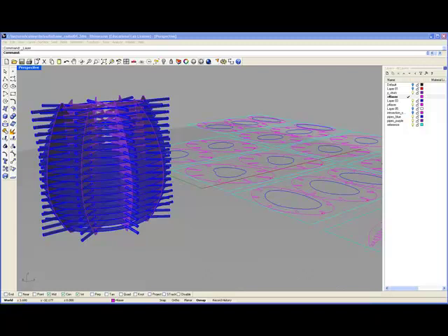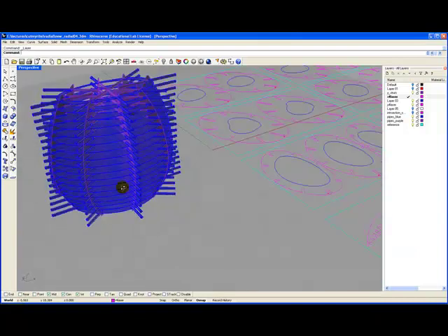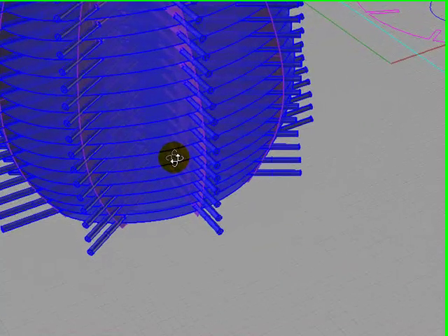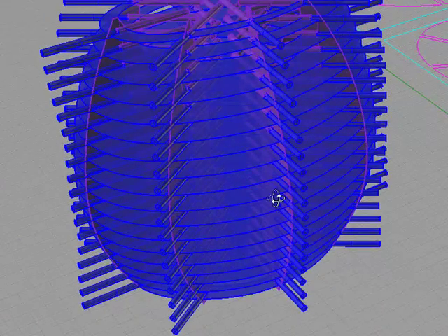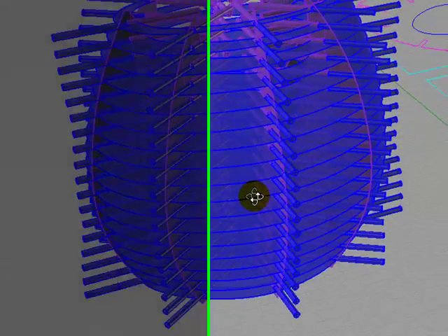associated with using the rib script, because the rib script does have some bugs in it as it relates to direction of the cuts of the ribs, and also as it relates to cleaning up and extending lines to remove artifacts from the cutting process. If you use this workflow, none of those things will be an issue, and it uses some of the same techniques that are found in the rib script. Notably, it uses pipes that you create that represent your material thickness to generate your cuts through a splitting operation.